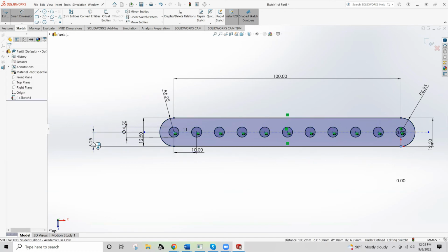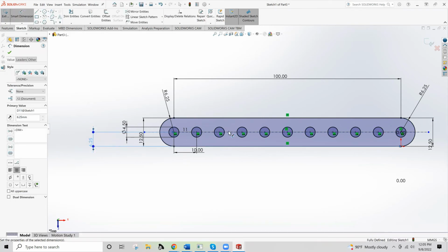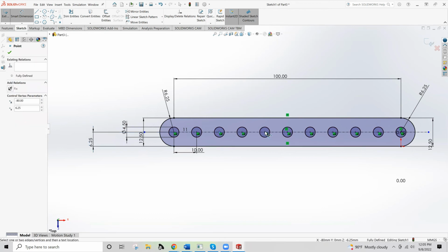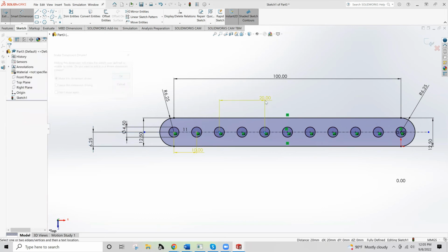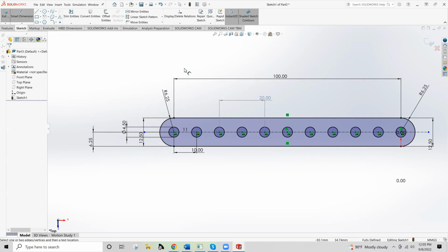All right. 6.25 in height. There we go. So now I can get an over definition, and we'll just randomly say the spacing between these two. There we go. So this is what it will look like. You will run into this very often, whether you're making a dimension driven or leaving it driving. Making a dimension driven means that it will change with the other things. So it will leave that highlighted, and even when you select off, it'll stay a different color.